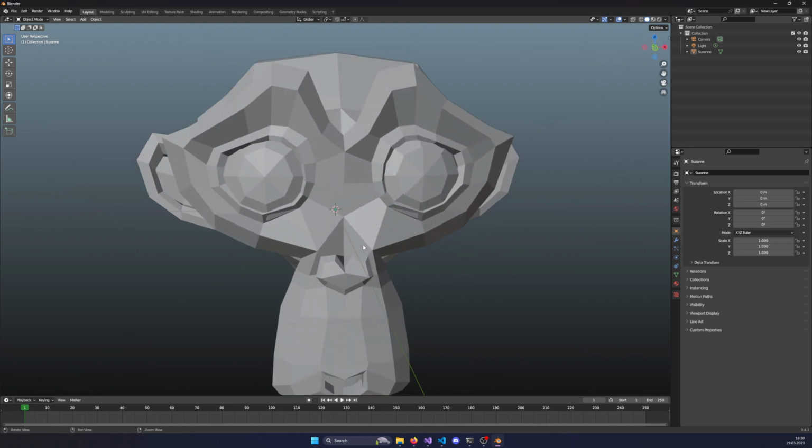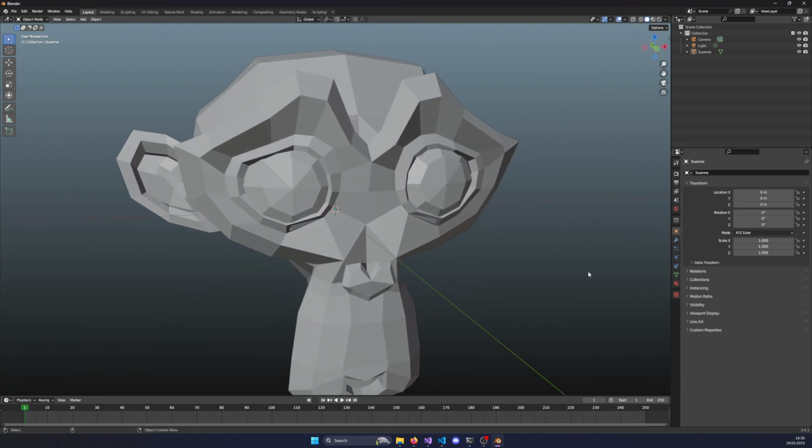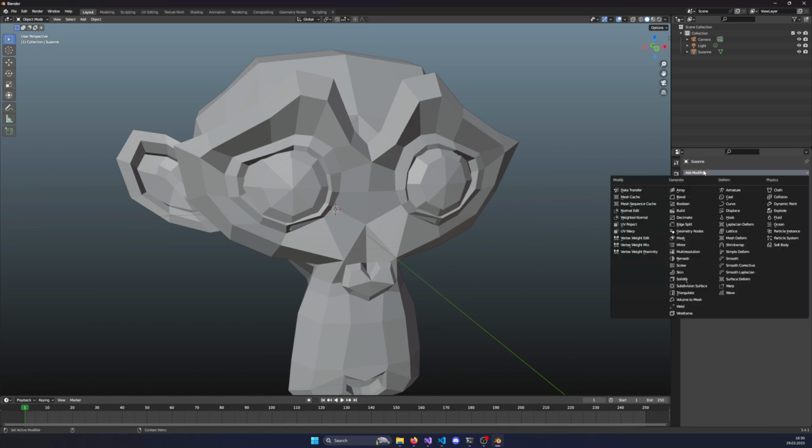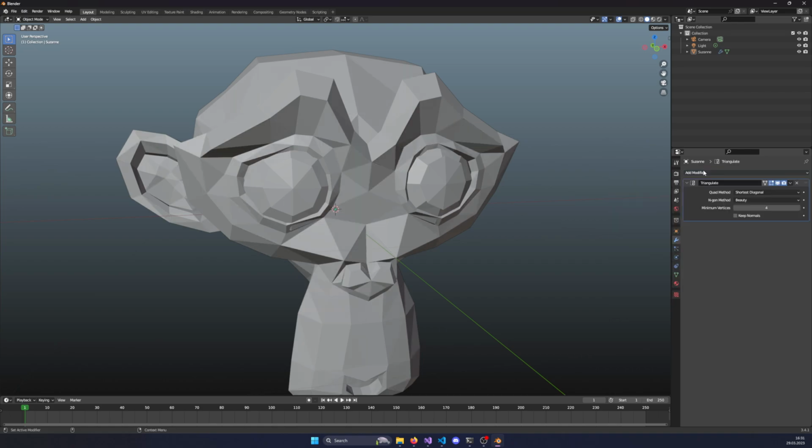However, for our rendering, we need triangles. Now there are multiple ways of solving that issue. The first is solving it directly in Blender. So what you could do is tell all your artists and all the people you buy 3D models from that they shall produce triangulated meshes. And it's not a problem for them. They just create Suzanne out of their imagination. Then they go to the modifiers and add Triangulate. They just type in triangulate and there it is.